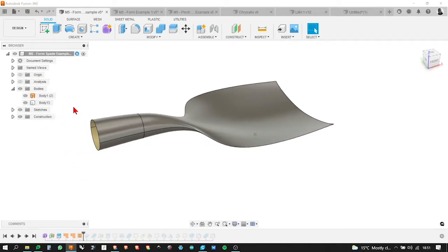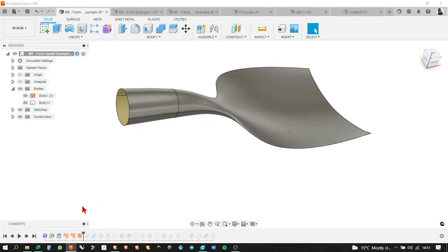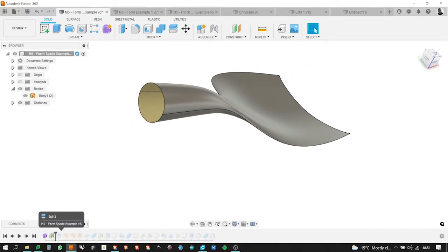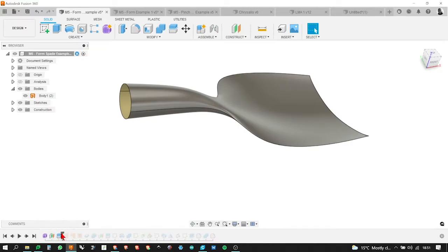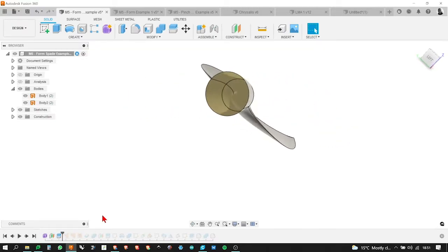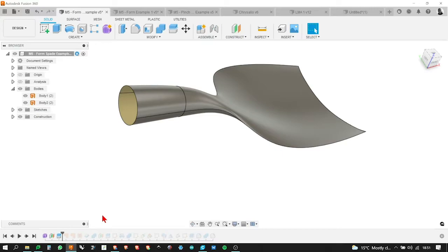So I've got, go back a bit, yes, so we're here, and what have I done here? I did a split at this point. That's an important thing, so I split it before I've done anything else, because I knew that part of it was going to be solid, and part of it needs to be hollow, obviously, to get that end of the handle in.